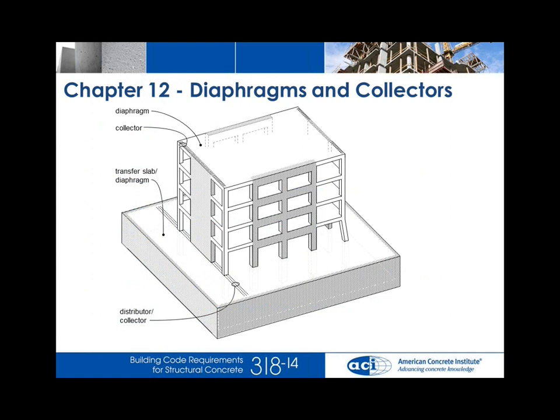A collector is an element that transfers shear forces from the diaphragm into the vertical elements of the lateral force resisting system. So there are collectors that may occur in elevated levels where you're picking up diaphragm forces and delivering them to the lateral force resisting system. And then there are collectors, or might be called distributors, that take force out of those vertical elements and transfer them into other diaphragm elements.